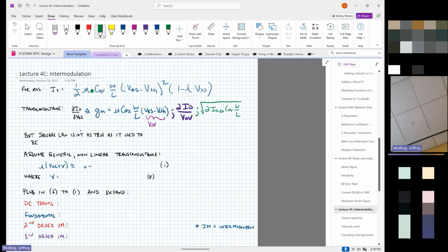All right, so the thing to take from this, if I look at that equation, is that the current is non-linearly proportional to the voltage because of that square factor. And even if that square factor is something more like 1.5, it's still nonlinear. So we're still going to see distortion if we put a big signal into this system.